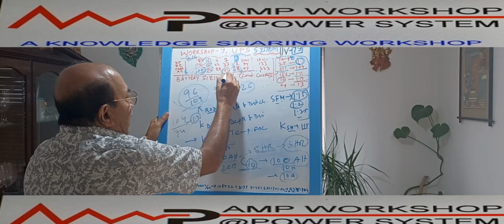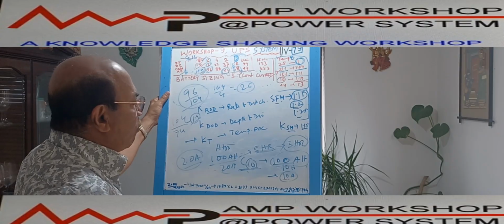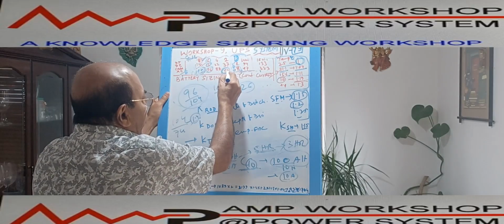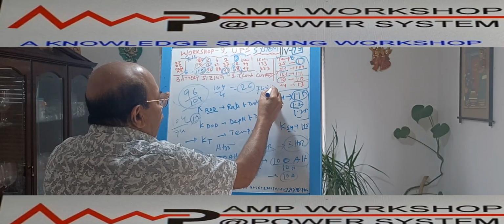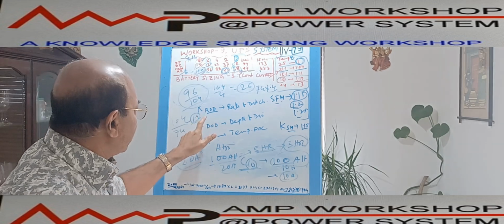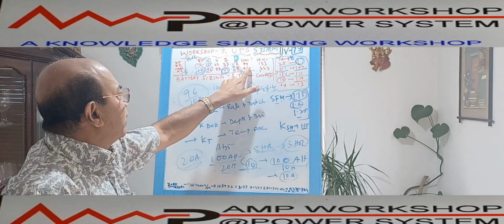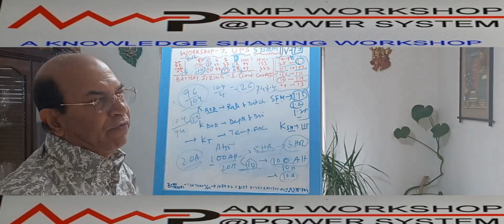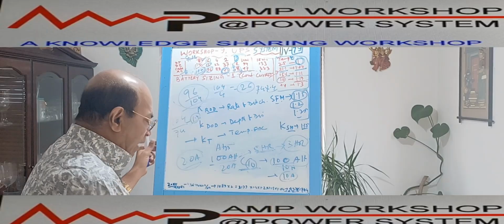Means if I take this particular 104 ampere hour battery, one assumption is that it will give the rated condition. But as it is giving 74 ampere hour, I have to multiply this requirement by 1.4 to get 104. So here this rate of discharge factor is 1.4. For a 1 hour discharge, this factor is about 1.5. So this is another factor we need to know from the manufacturer.